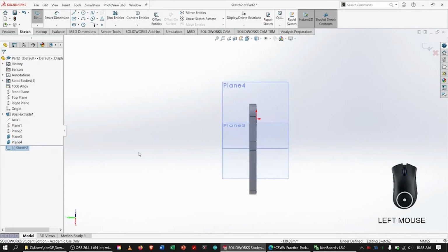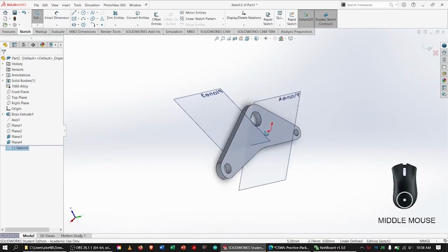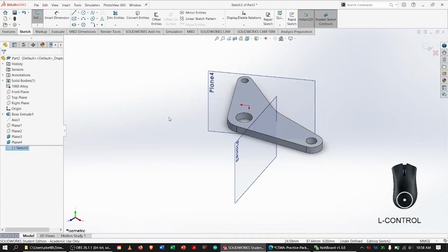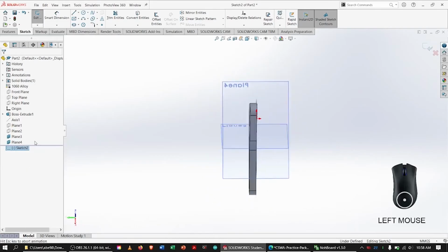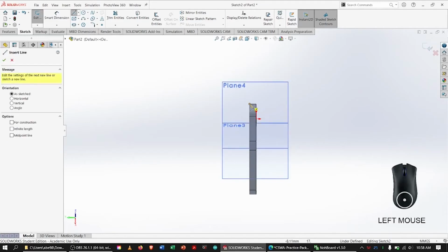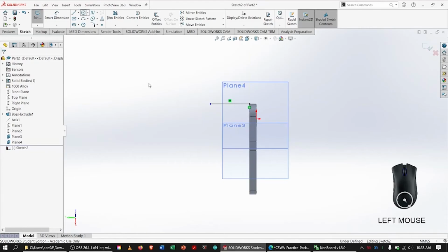going to view it normal to it, and SOLIDWORKS sometimes gives you a slightly interesting way of viewing the plane normal. So we want to sketch on this side in order to make the feature actually show up properly in an isometric view. So the first thing that we want is going to be a line. So line here. Then we want the set of two circles.